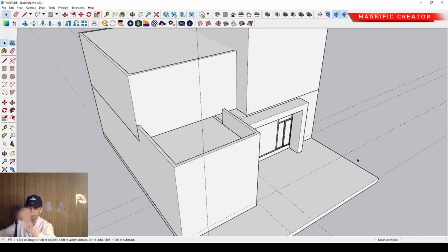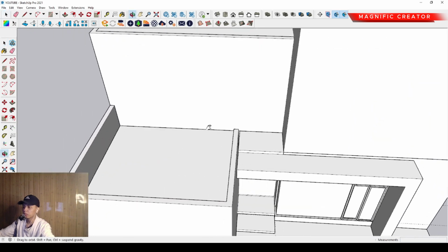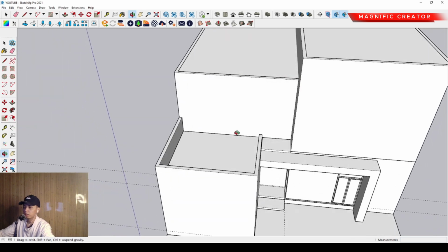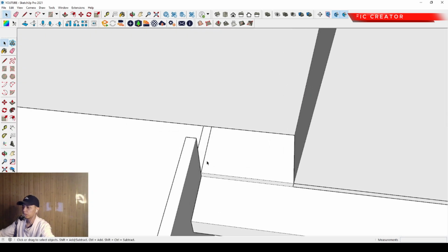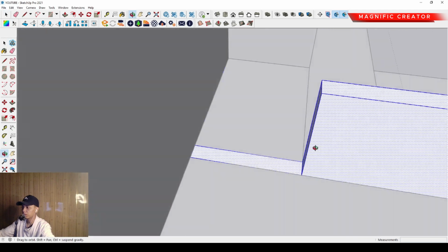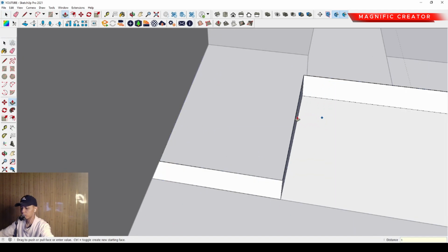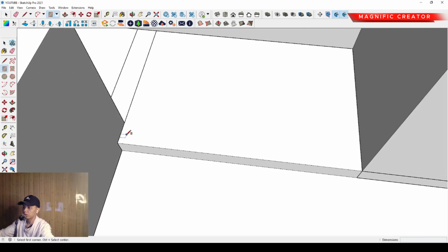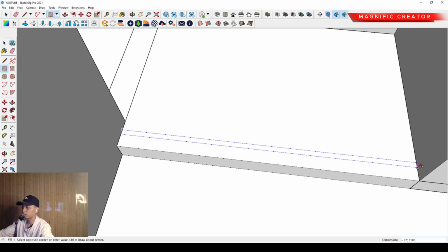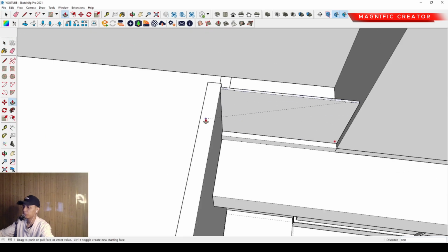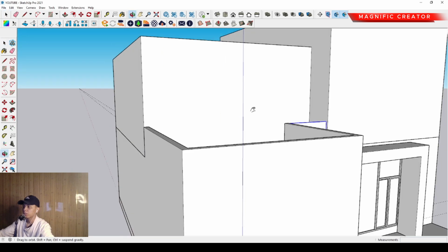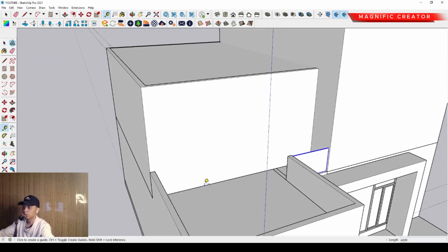Okay, so then we can make the another space of it. Okay, we can make the glazing, but before we make it, we have to push it to the back around 150mm, something like this. Then we can make the glaze element here with the thickness around 20mm thickness. Then we can just make it group, and okay, we can make the another additional door.